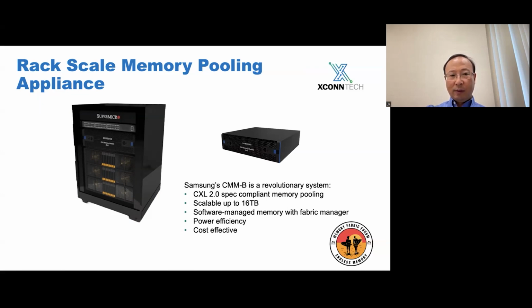So the servers don't need to have a huge amount of local DIMM. When they need memory, they go to the CMM-B, the memory pool, to request the memory resource and keep the application running. This is the system Samsung used to demo an SAP HANA in-memory database and show a big improvement because of the CXL memory pooling, which provided all the benefits of low latency and high bandwidth memory access.